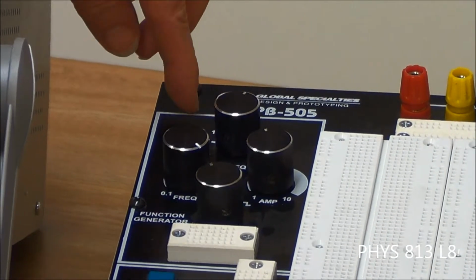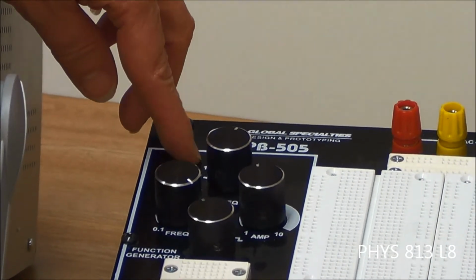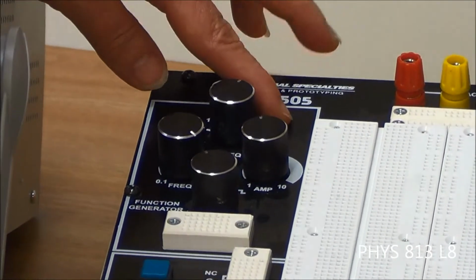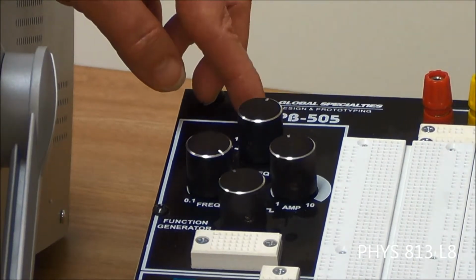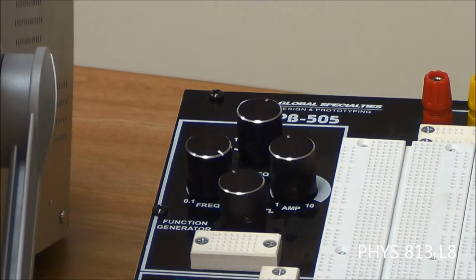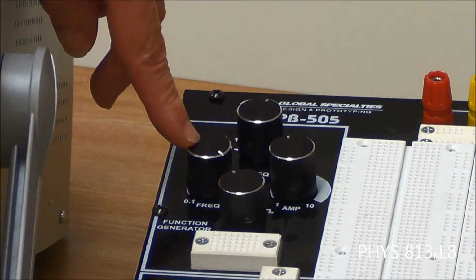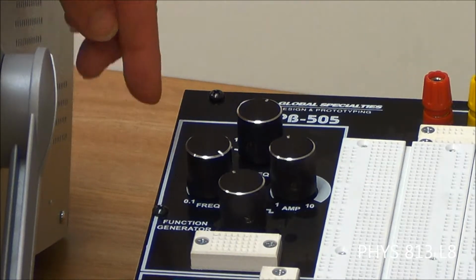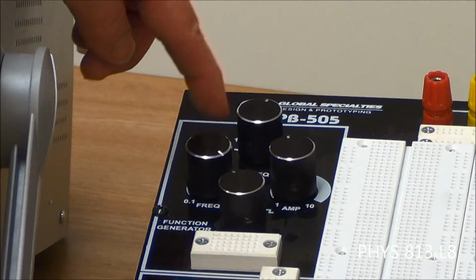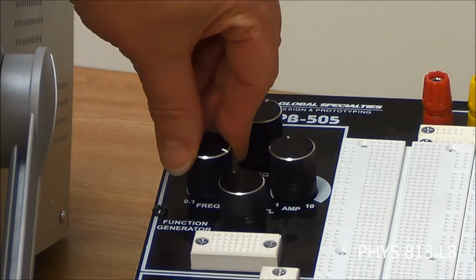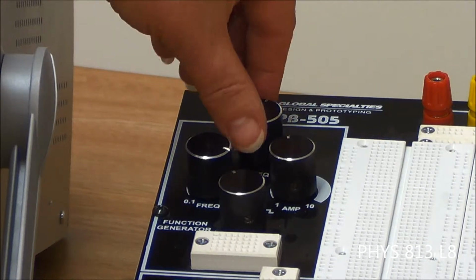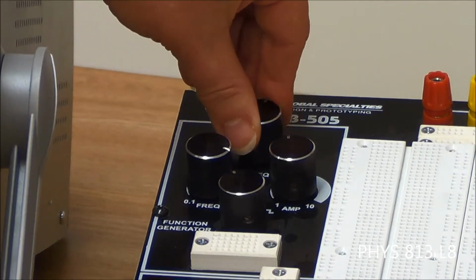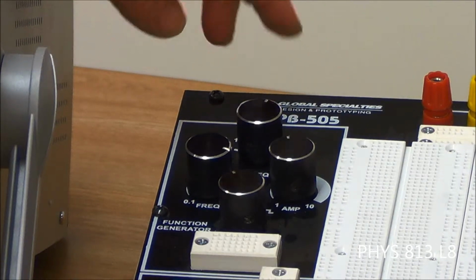This top dial can be moved from 1, 10, 100, 1K, 10K, and 100K. So this is the frequency, the major divisions. I have it set on 1K, which is what we're going to use in a little bit. 1K is 1 kilohertz. Now, this second one here on the left also says frequency, but on the left it is 0.1 and around to the right is 1. So this knob is a continuous moving knob. This one up here at the top sits at a particular position, so it's not a continuous moving knob.